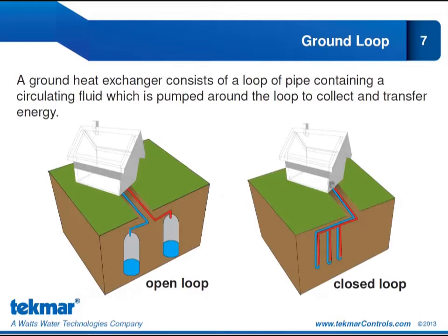It's the least expensive to install and has very high efficiencies. However, you have to have an ample water source, and there are inevitable concerns about water quality. So we have to take a look at what types of impurities might be in the water, if there are minerals, what are the quantities of minerals and particles, is there organic matter that we need to worry about? All those can damage the heat pump system.